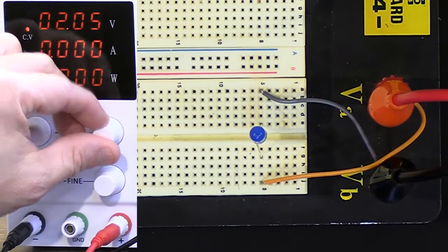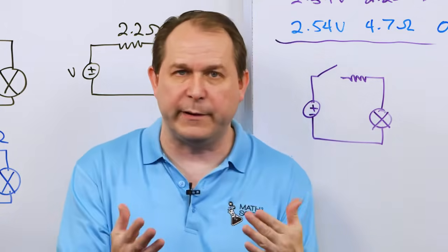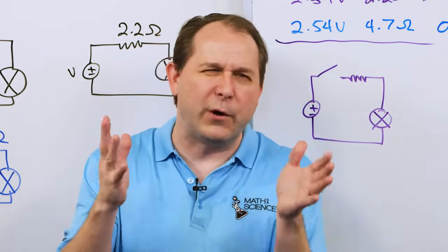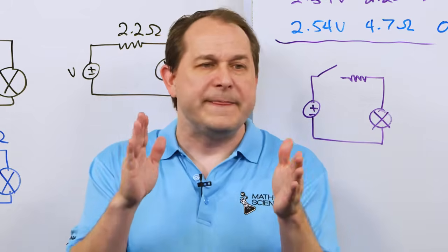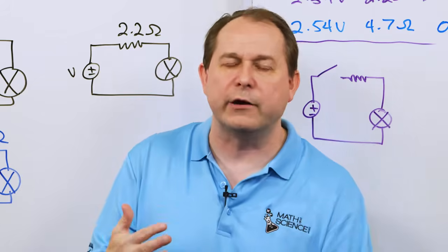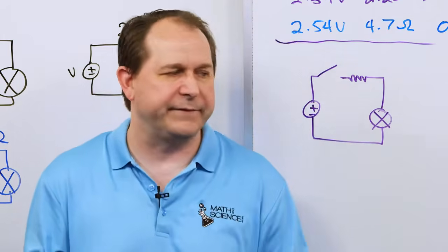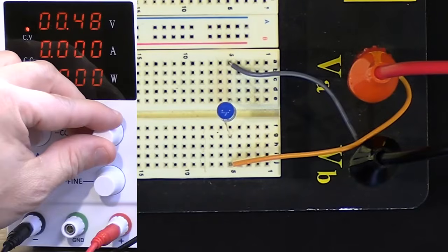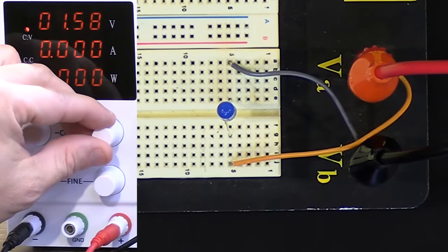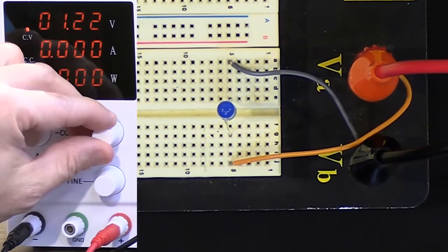It does dim a little bit. There is a range where it will begin to light up, but mostly diodes are an on-off situation. There's about a volt, or about 3/4 of a volt, in a range where it will begin to turn on. But once it's on, it doesn't really get any brighter, and once it's off, it's just off. There's a narrow range when it turns on. It's sort of an on-off kind of deal. So it does nothing at all until we get up around 2.5 volts. Then it starts to come on, then basically it's fully saturated.